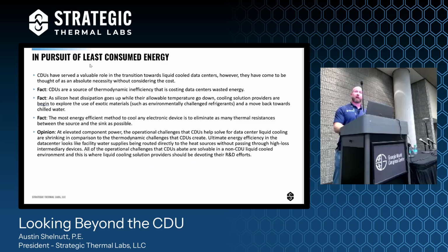The other thing I would point out on that topic is two things. One, obviously, rack filtration is an option. We have a solution for that. So you can filter water as it goes into the cold plates. But more importantly, we should consider how much energy it requires for a data center to maintain high quality water compared to how much energy goes into chilling that water, right?